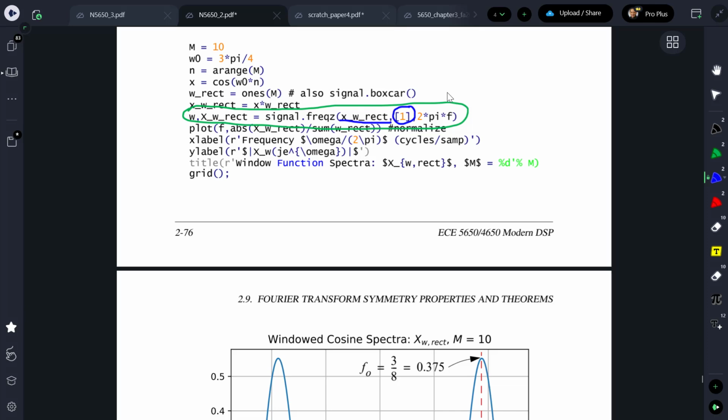So this is a repurposing of the freqz function that was defined earlier, just putting the signal you want a Fourier transform of in place of b, which is the numerator values in the ratio of polynomials in powers of e to the minus j omega that we saw last time. You used freqz also in the homework, right? It's not exactly a magic box. It's something that I'd like you to more fully understand, but really what it's doing is taking the FFT on the first set of coefficients and then on the second, and then dividing point by point. I can talk more about that later.